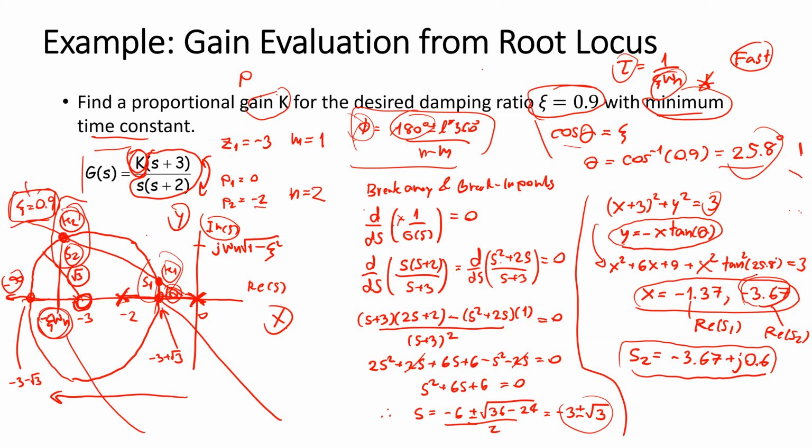But what you can see is the real part is big, but the imaginary part is quite small. The damping ratio is big, it's almost 1, and the angle is very small. So it makes sense that the angle is small. It makes sense that the imaginary part is not that big, and the system not gonna extremely vibrate.